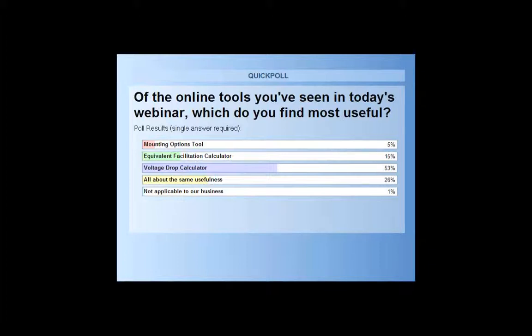And then the next question: what current draw at what voltage is being used for the voltage drop calculation? I think that's asking what's the starting voltage, which is 24. That could be. Yeah, that's the 20.4 answer again. And if the attendee who asked that, if that's not what you were asking, at the end you'll see both Krista's and my email address, and also in the follow-up survey you'll get my email address. If you want to just ask that question again, we'll try to get more clarification.